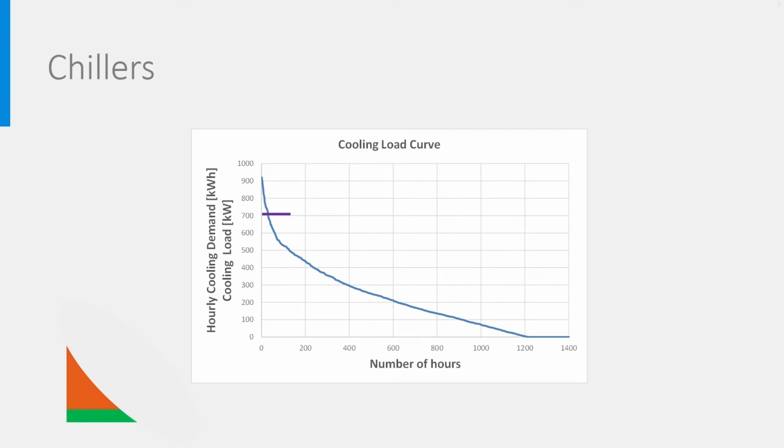What can be done is to use a renewable cold source as basic cooling instead of for peak and use the chiller above a certain load. This way, a maximum use of environmental cold can be achieved, for instance, like here. The nice thing is that ATES technology, or the use of surface water or of night air, is not very expensive. In fact, it may be cheaper than a chiller.